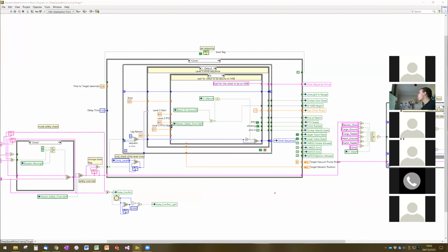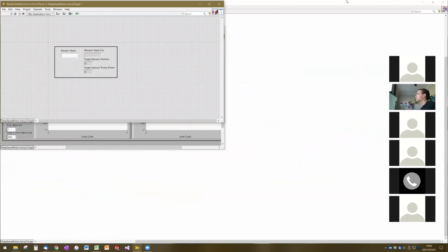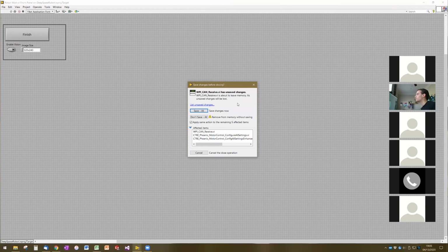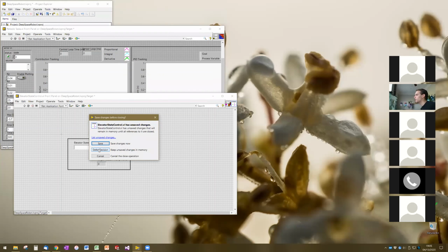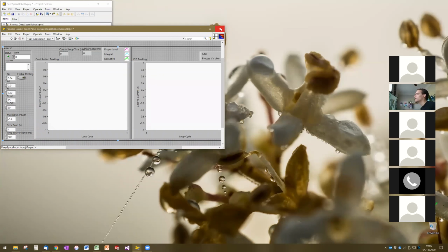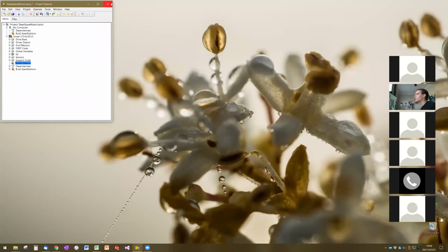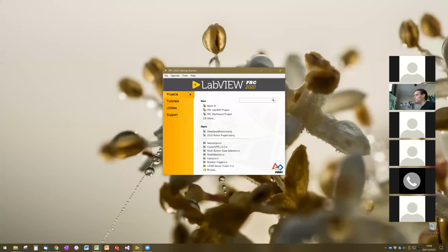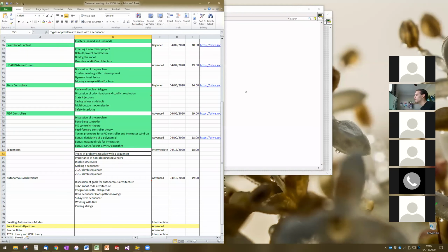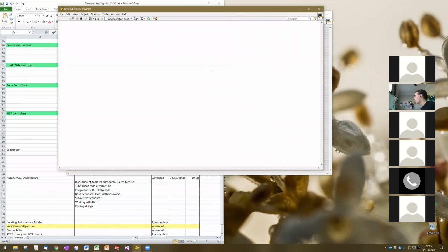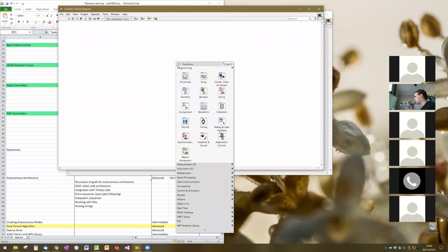So we're going to go ahead and move on to autonomous. Although I want to mention one other thing that I keep forgetting to mention in every single workshop. I just want to show real quick, and I just had it on the schedule today so we cover it, is a disable structure. So if anyone's familiar with text languages, you can comment out code. A disable structure is LabVIEW's equivalent to that.